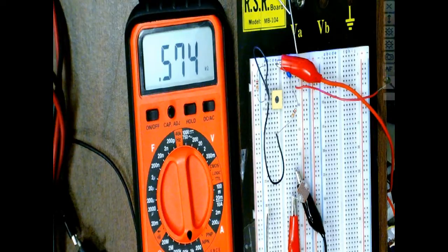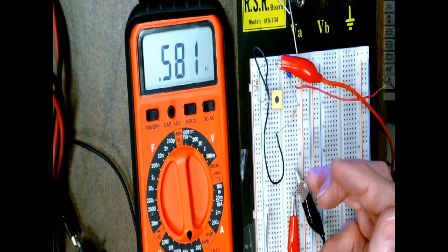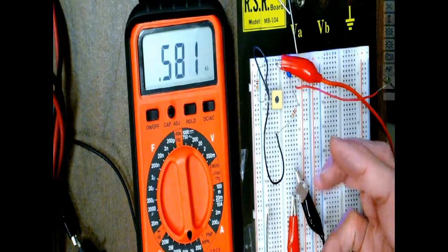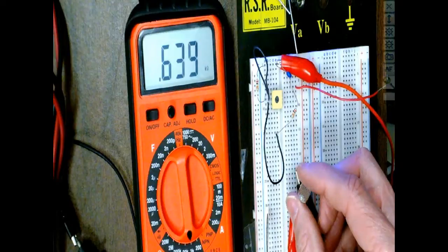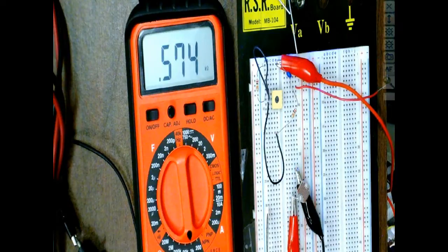If it's summertime and it's 5 o'clock and the lights are on out there, then those guys are still using timers. But now what they do is, if you ever looked at the top of these things, they've got this photo resistor. Of course, there's electronics to it. There's no way in the world this guy right here could control a street light, but it can be the sensor that controls the street light. This sensor could pick up a relay, and the relay could run the street light. So all our lights outside now come on automatically at night, and they go off automatically when the sun comes out.